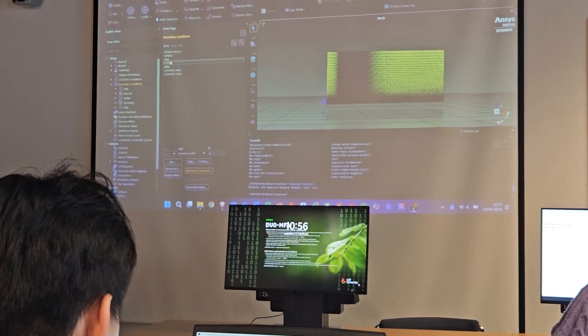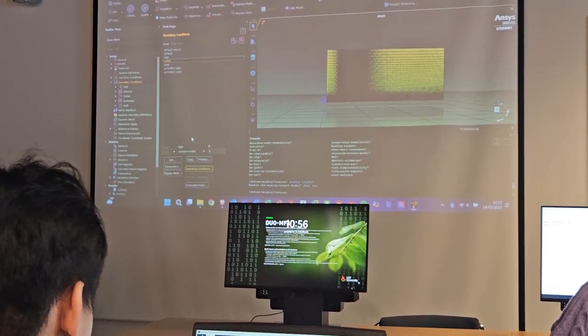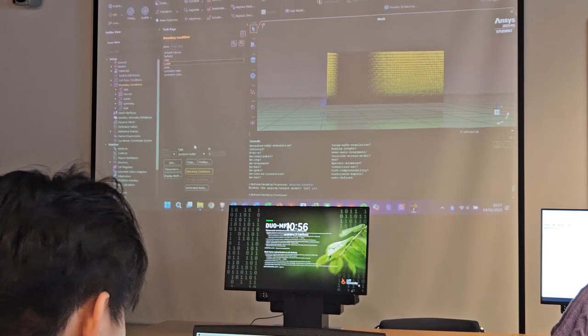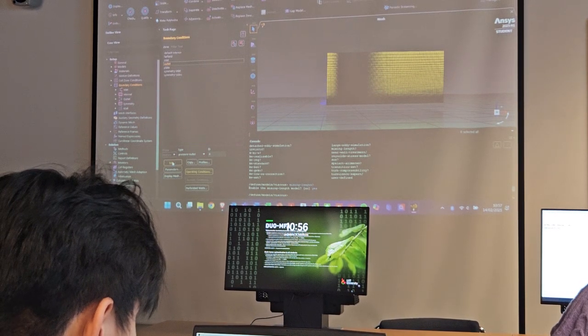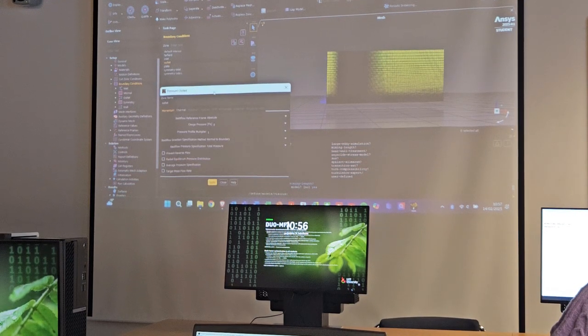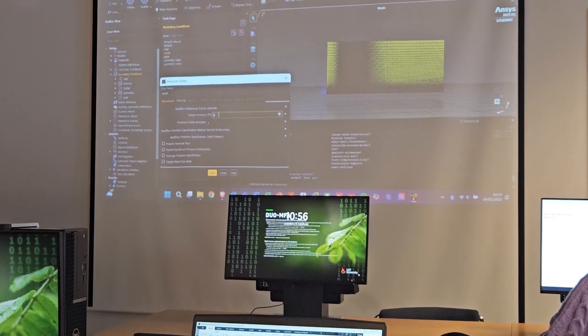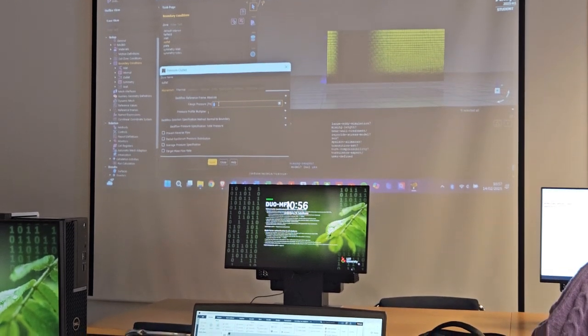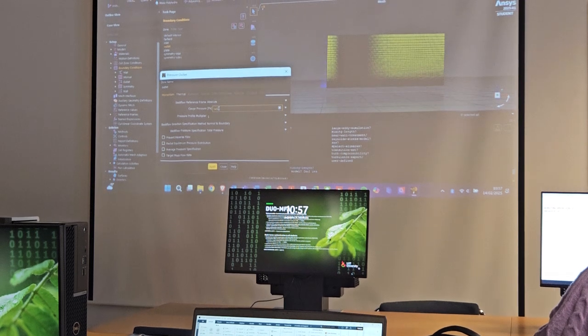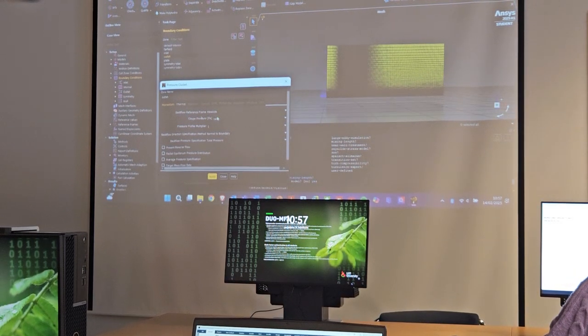It is the outlet. The outlet is a pressure outlet. That's correct, since we need to set the static pressure of the outlet. We can click Edit on the bottom in order to set the gauge pressure, so the value of the static pressure at the outlet. That is 1 bar, so 1e5, that means 10 to the power of 5 pascals, so 1 bar.